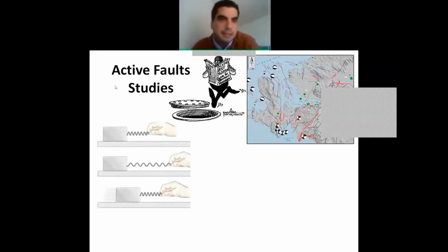Another thing is, even though we do seismic hazard assessments, one of the big issues is that we should put a time constraint on these assessments for places where the threat is imminent. So finding out whether this fault is in a stressed time or the stress is already released on that fault is going to be very crucial.